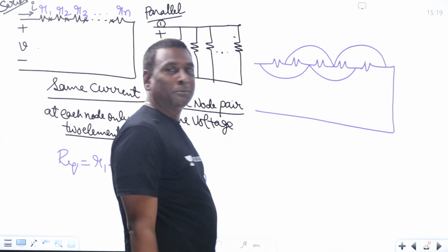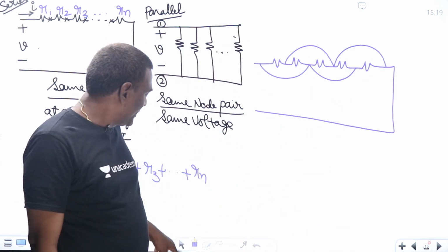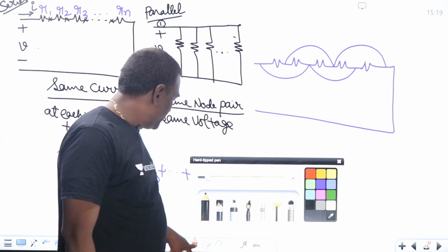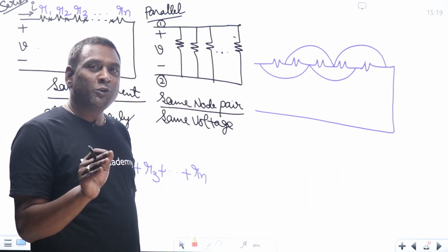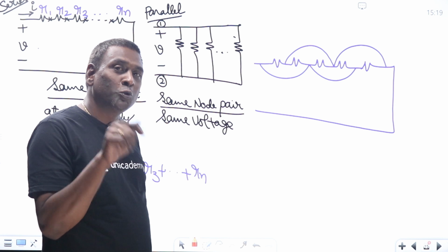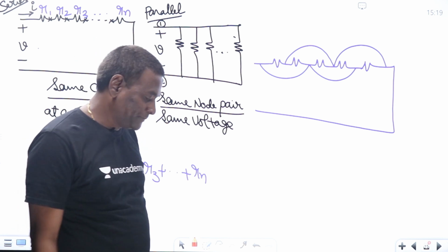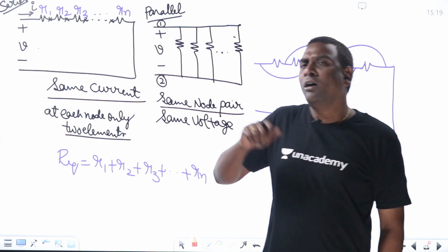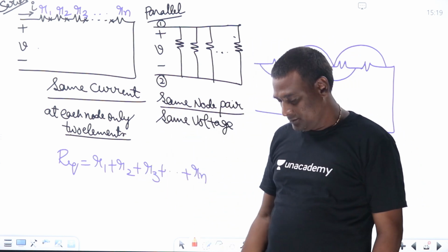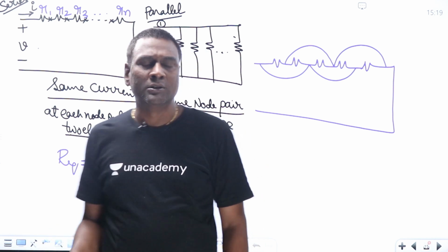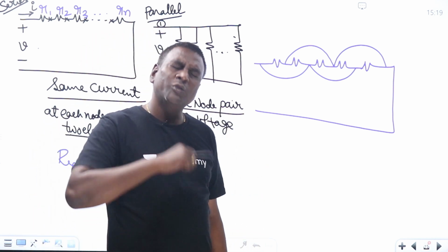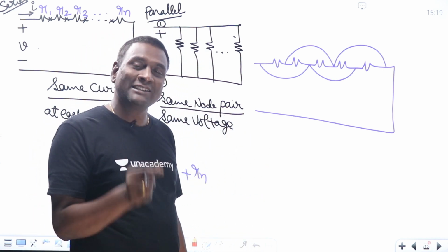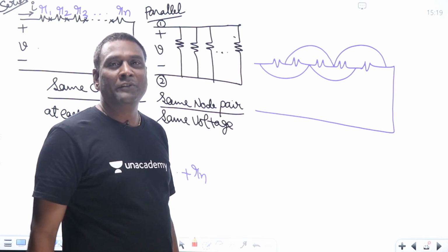Are they connected in series or parallel? Parallel now. Because one logic I'll tell you, simple. Whenever you have long short circuit paths, this is very important, keep that point in mind. You can make a note of it. Whenever you find long short circuit paths, give node numbers. This can be extended to machines also. Wherever you have long short circuit paths, give node numbers, then the problem will become very simple.